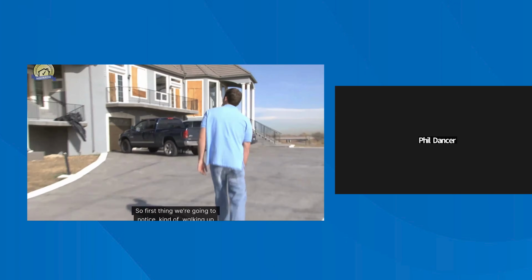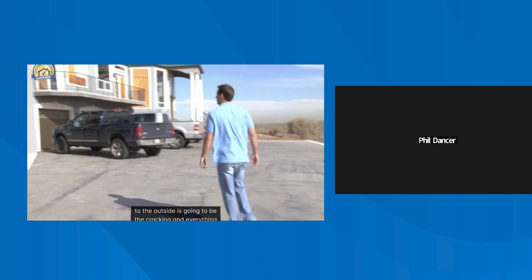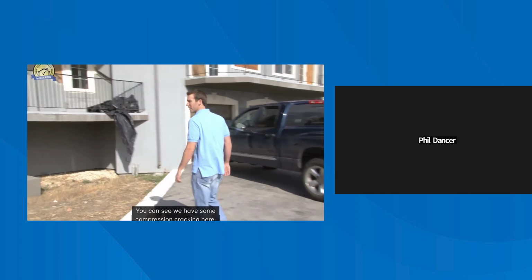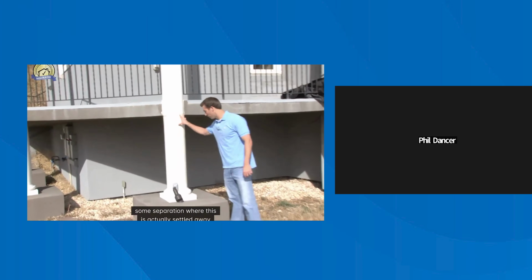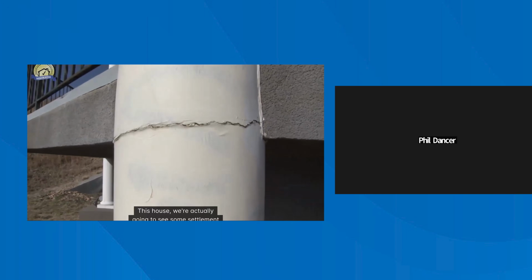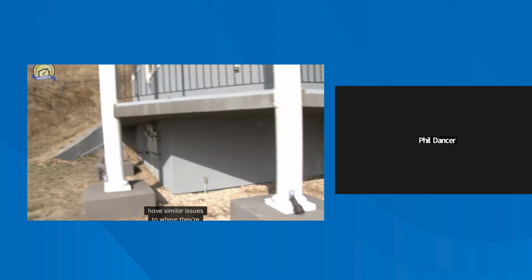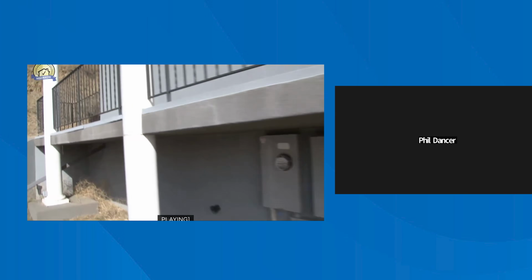So the first thing we're going to notice walking up to the outside is going to be the cracking and everything else that's not only in the stucco but also in the pillars. You can see we have some compression cracking here, some separation where this has actually settled away a little bit. This house we're actually going to see some settlement and heaving, just both different signs of some vertical movement that we're running into. You can see all of these pillars here kind of have similar issues to where they're getting that vertical movement.